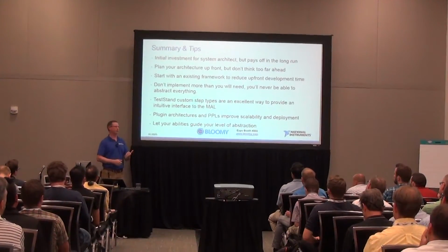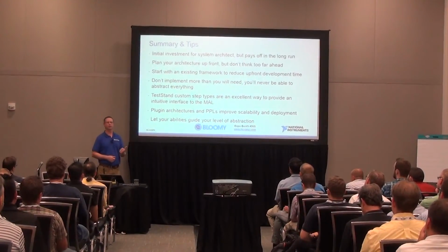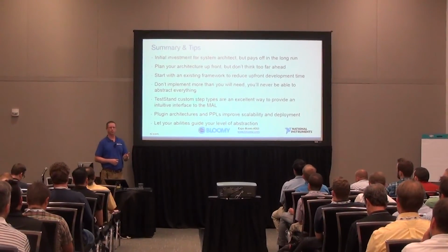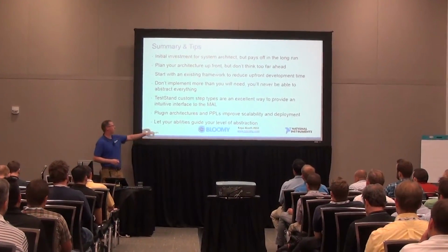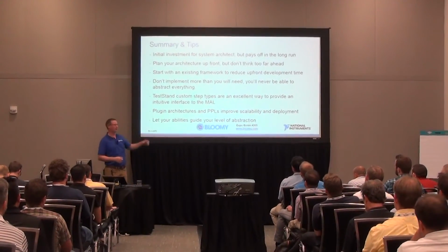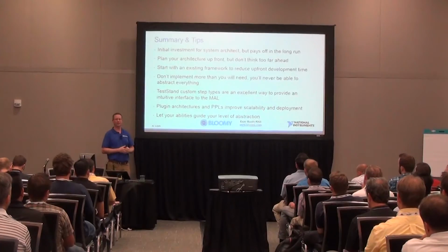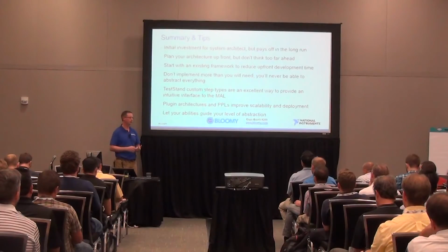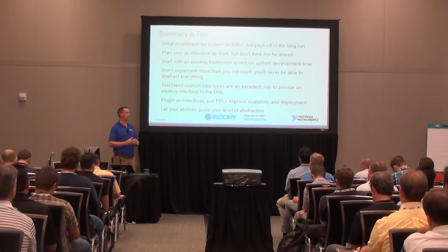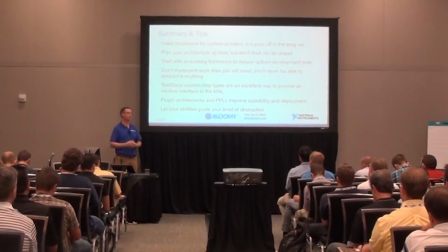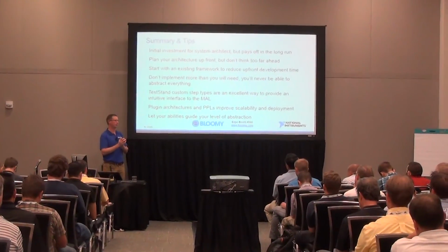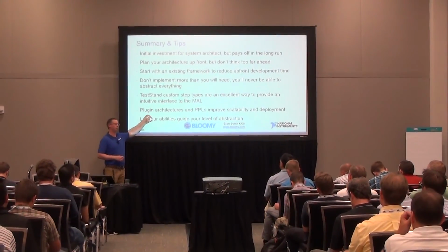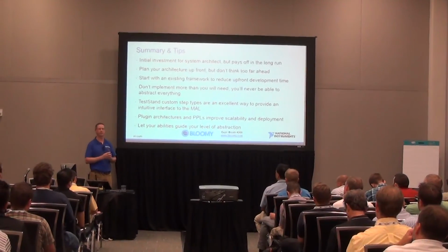Test and custom step types are, if you're using TestStand, an awesome way to implement that measurement layer. And when you're using plugin drivers, packed project libraries, there's some people who really love them. There's some people who really hate them. With TestStand, they're a huge help for deploying because you have one file that is all compiled code. You don't have to worry about searching. You don't have to worry about your VI library on one machine being on a different machine. All of the dependencies and everything are wrapped up into that PPL. And so when you're deploying plugins, this is really helpful because you can make sure that your plugin is always going to work and always has the dependencies that it requires.